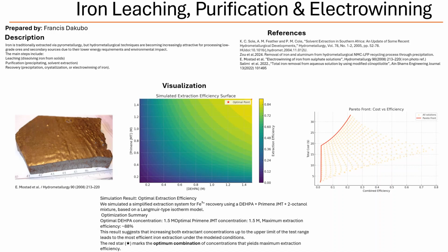What kind of factors? Well, first they lay out their optimization model mathematically. They define 2 objective functions, J1 for the cost of the chemicals, and J2 for the efficiency of iron removal. Then they identify the control variables, which are those addition rates for oxygen and zinc oxide in each of the 4 reactors they're using. And of course, there are constraints. Constraints like what? Things like flow rate, temperature, and the acceptable concentrations of different ions in the solution. Copper, ferric iron, ferrous iron, hydrogen ions, all that good stuff. So it's like a recipe with strict limits on the ingredients. In a way, yeah. And to describe the actual chemical reactions happening, they use dynamic equations that track how the concentrations of those ions change over time in each reactor. Sounds like a lot of equations. It is, but it's all based on fundamental principles, like the conservation of mass and the kinetics of the reactions.